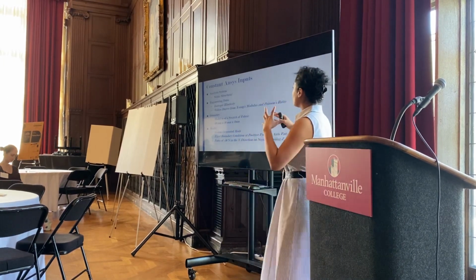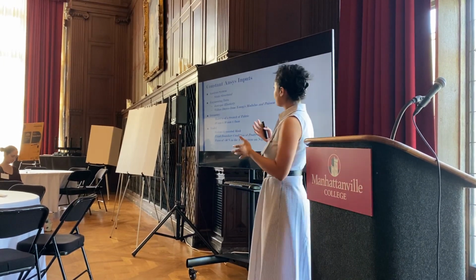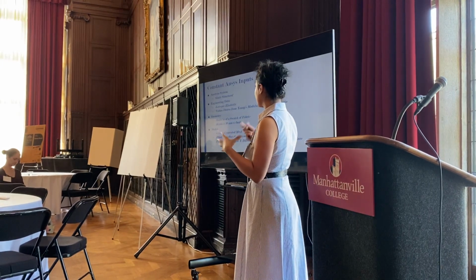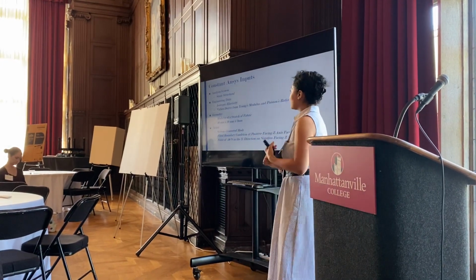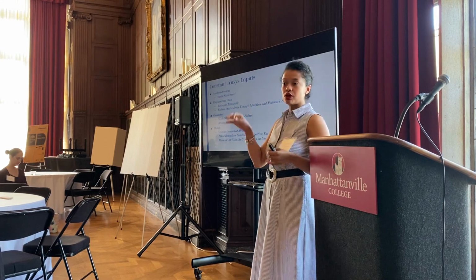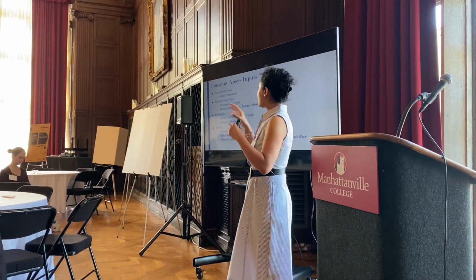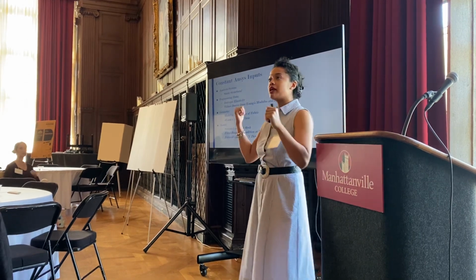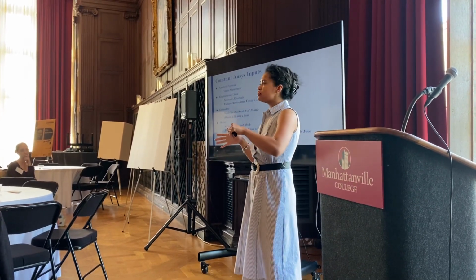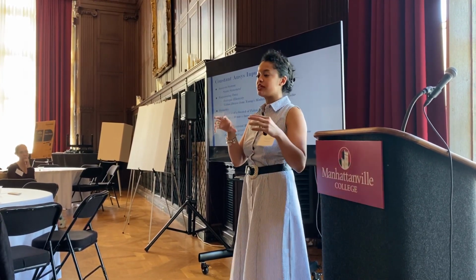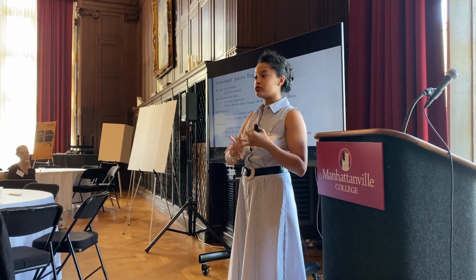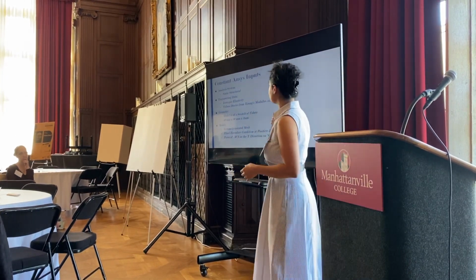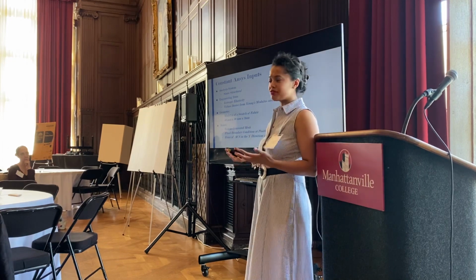All right, so when we did the rounds of experiments, we had certain things that remained constant. For example, in the analysis system, we used a static structural analysis. For our fabric simulation, we made sure it had isotropic elasticity, and we had values such as the shear modulus based on Young's modulus and Poisson's ratio. For the geometry, we just kept the same dimensions of the fabric.